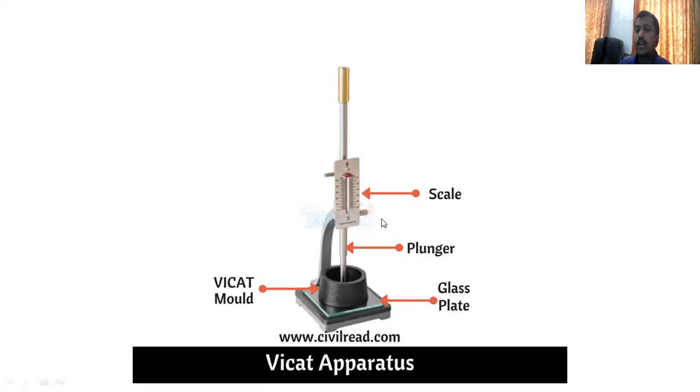What are you going to do? You are going to take 400 grams of cement and dry mix it. After dry mixing, you remove any clinkers or lumps that are present. If there are any lumps, you can remove them using the dry mixing technique.